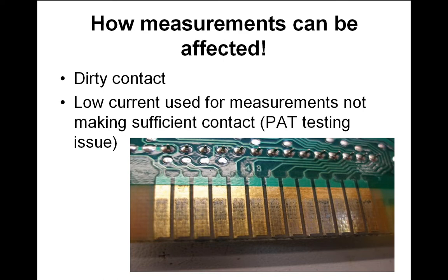Callum said something interesting: just clean it with your fingers. That's what I was told. Okay, that's one thing, but you have to bear in mind there's potentially grease on your fingers, and grease could have insulating properties as well. It's just something to bear in mind. But obviously, clean it up as best as you can with your fingers, or if you've got an overall or whatever, just to move the dirt away to get a contact. It's important. Thanks for the contribution, Callum.